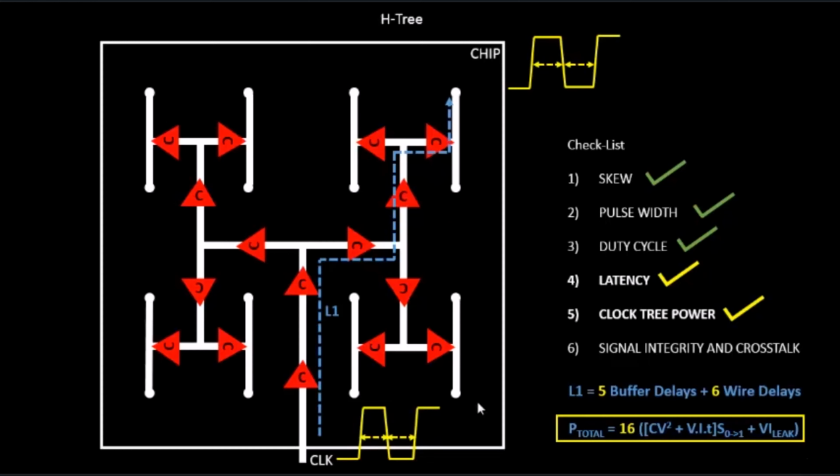Imagine a clock tree with millions of flops. Then there would have been millions of clock tree endpoints that we would have optimized for, and the amount of power saved for that many clock tree endpoints is huge. So we can now understand how removing one buffer, or basically using fewer buffers, directly impacts the total clock tree power. And by saving the clock tree power, you actually save the complete chip power, because the clock tree consumes about 70% of the complete chip power.